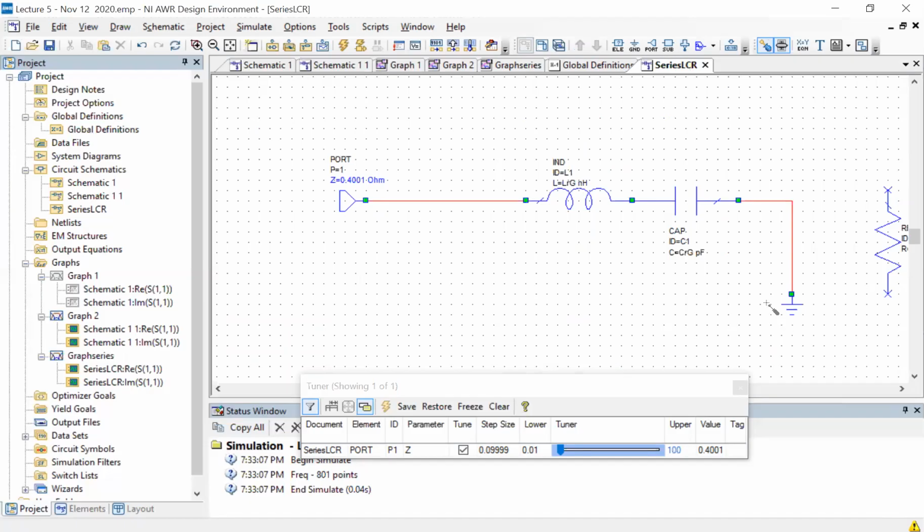Now, having said that, of course, you can choose L's and C's, just like you had in the case of the parallel circuit. Remember, Q also had this expression, which was R over Z of R, where Z of R was square root of L over C. This is for Q parallel, okay?